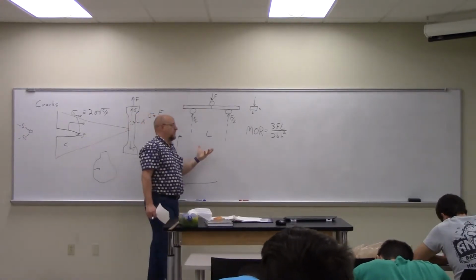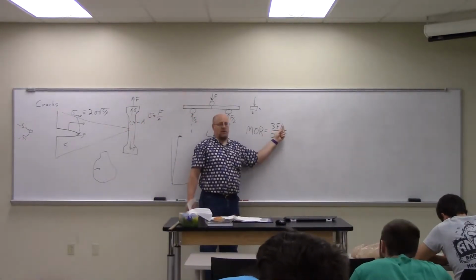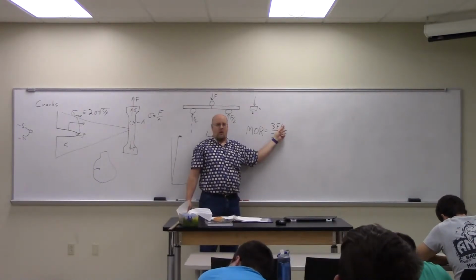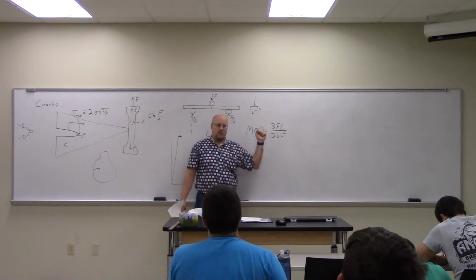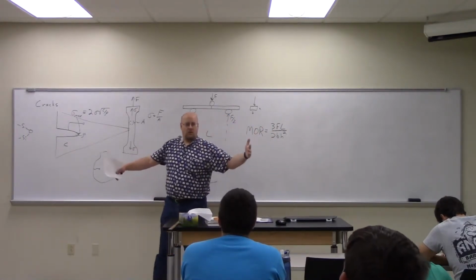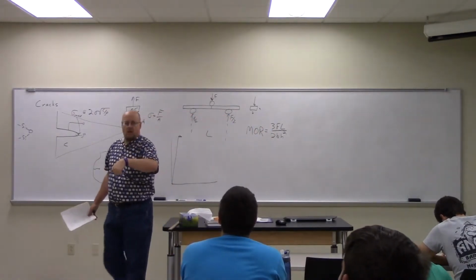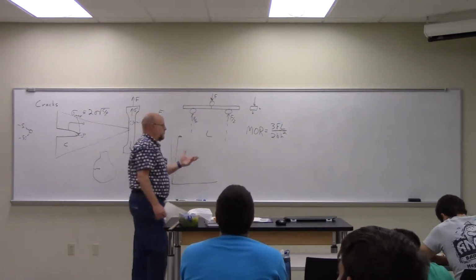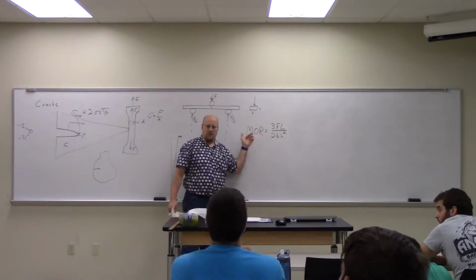Similarly, if I have a particular sample, and if I increase L for a particular kind of material, then it's going to take less force to break it. Right? The further L is apart, the less force it's going to take to cause that thing to break in the center. Because the modulus of rupture then is a characteristic of that material.